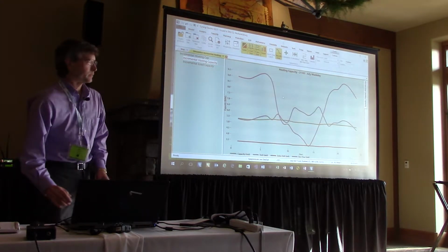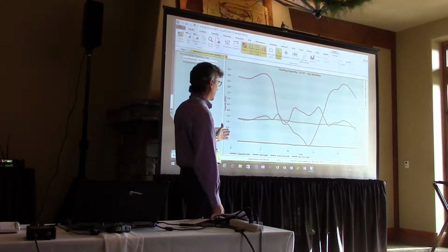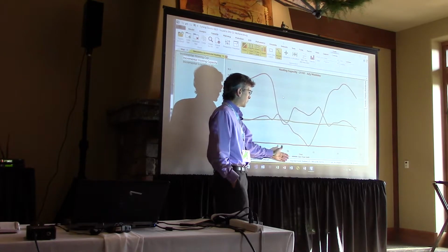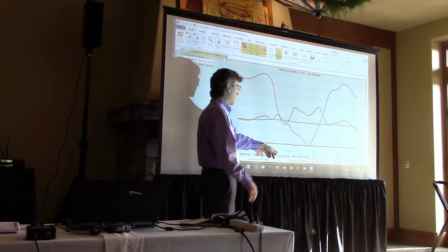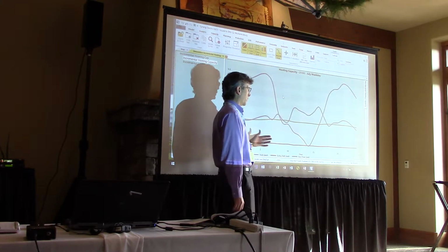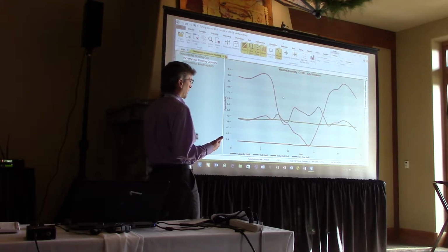And now this is looking at just this section, and this is going to be a day in July. So it's a July day. Irradiance-wise, as far as the sunlight goes, it doesn't matter that it's a weekday. But the reason a weekday matters is all my loads. Because the loads throughout the system are going to have an impact on the hosting capacity.